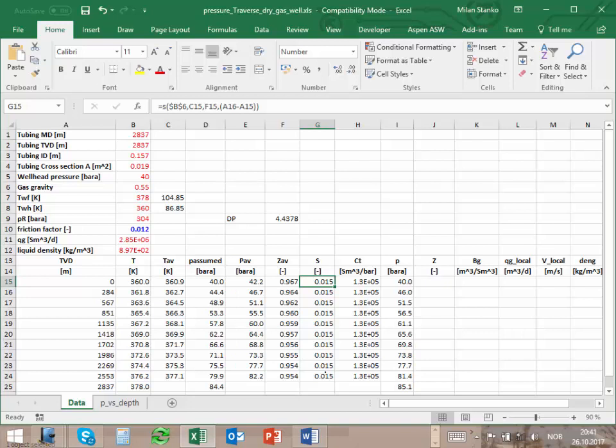And now I start my calculations from the point where I know the pressure, the wellhead pressure. And I know the rate, and I move from the wellhead pressure 284 meters down and calculate that pressure. Now I have this pressure, and I move 280-something meters down again and calculate that pressure. Each one using its own C T, its own S, and its own inlet pressure. And you see that the C T doesn't change that much with every section. There might be some variation, but not much.